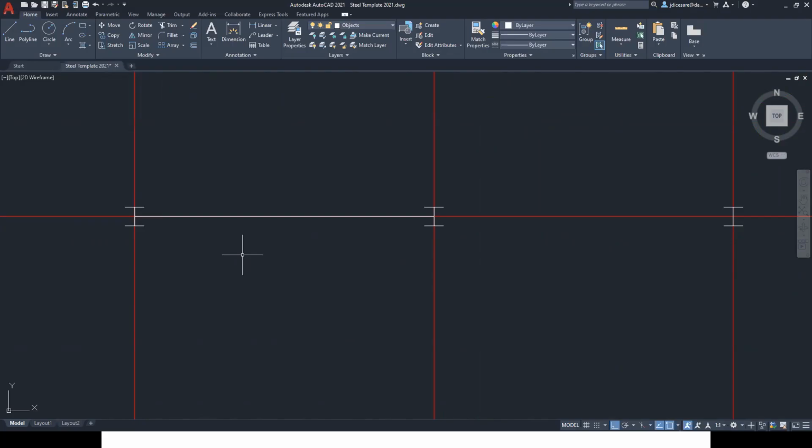Now, in the old days, guys, before we had these drag points in the newer versions of AutoCAD, people would have to draw a line, trim the line. What I used to do in the old days, instead of doing that, I used to use the scale command. I would take this, find the midpoint, there's the midpoint, and then put something less than 1.95, you understand?